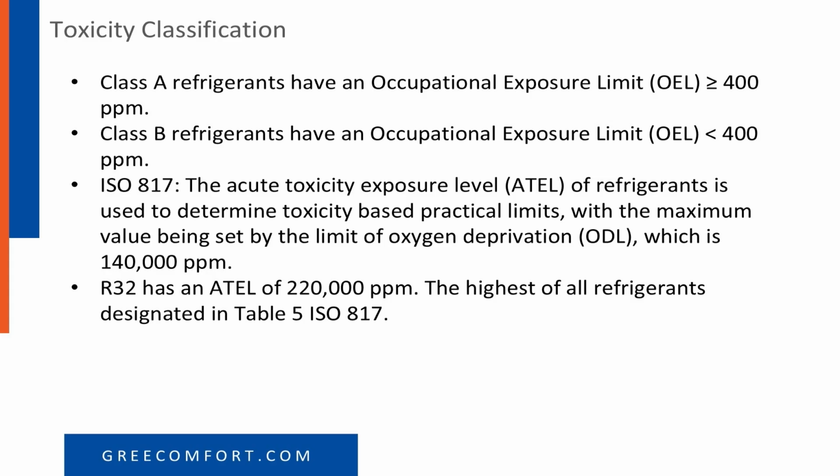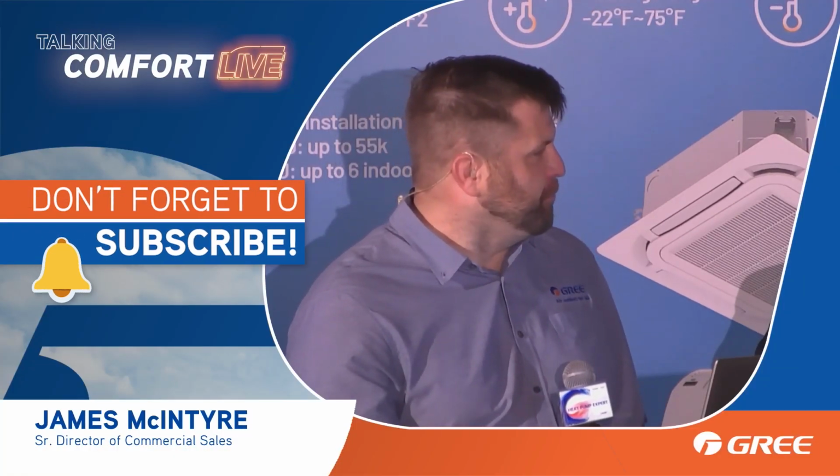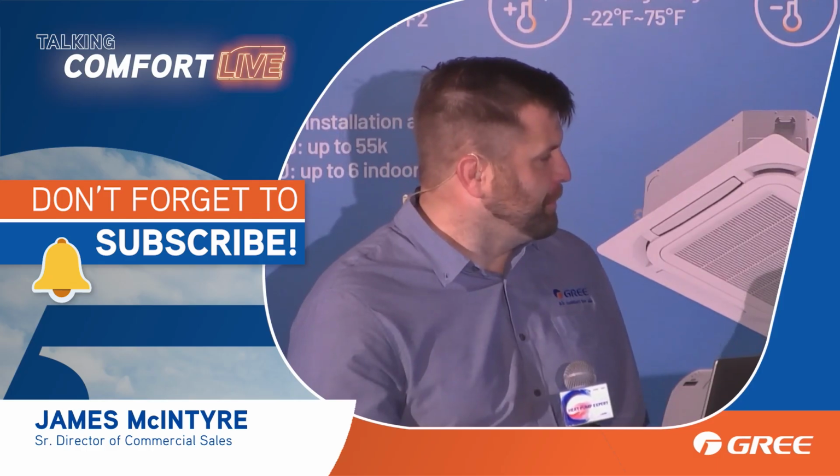So when I left my recovery tank cracked open by accident, and it was in the back of my truck and filled the cabin, I started getting lightheaded, so you turn it off. If that's never happened to you, do you even do this for a living? But what you're saying is that the toxicity, I would basically have to start getting lightheaded and stuff like that. Yeah, absolutely. The lightheadedness will come from the fact that you're being deprived of oxygen, not because of any chemical reaction within the body.